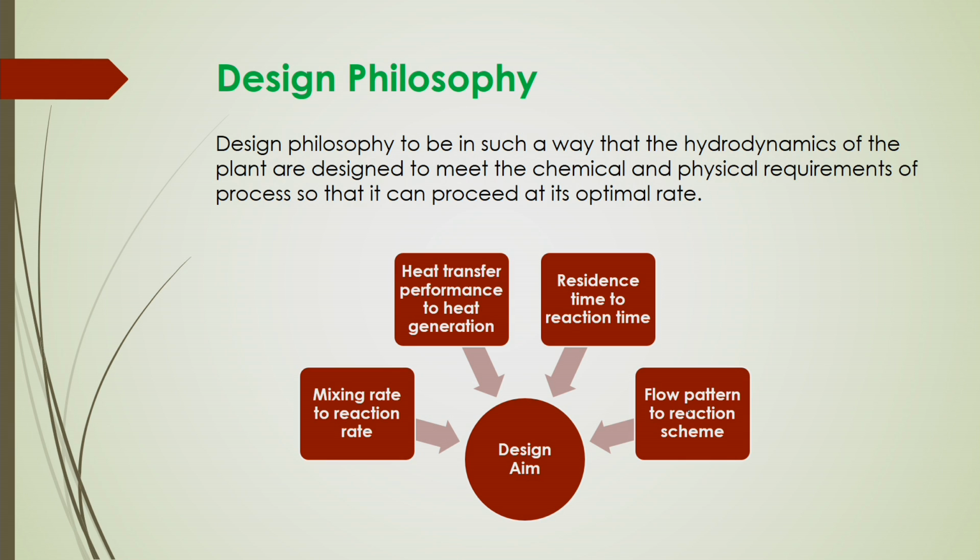Of course, that mixing phenomena will give you the residence time distribution, how long the fluid particles will be residing inside the reactor. For fast reactions, it may be low, but for physical operations where more residence time is required, in that case the residence time is to be considered based on that mixing phenomena and other design. Sometimes you have to use some provisions in a reactor, so that back mixing will be less. So, that is why in that direction you have to design the process.